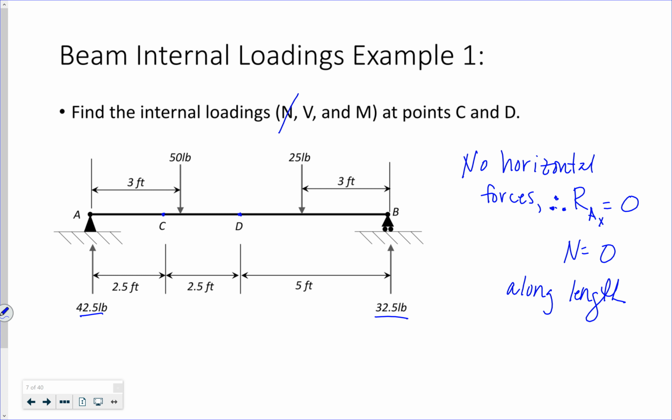So I'm going to ignore it, and we're generally going to ignore axial forces in beams because beams are not there to be axially loaded. They can have an axial load within them, but they are there generally for shear and moment, for bending, flexure. Those are all words that you might hear. The primary loads in a beam are shear and moment, not axial.